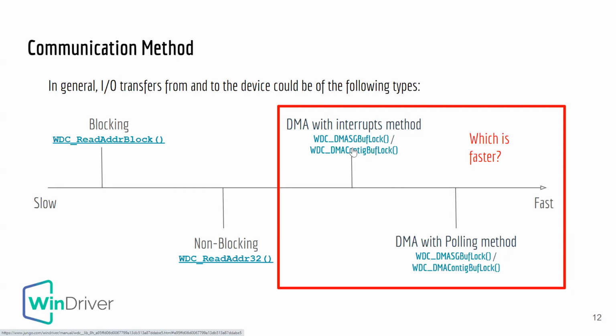So in this type of DMA, there is a transfer taking place. Once it ends, it raises an interrupt to the CPU instead of the CPU continuously asking for the status. So what is polling? Polling involves repeatedly checking a status flag or register to determine if a DMA transfer has completed. This method requires constant monitoring by the CPU, which can introduce overhead and inefficiency in handling data transfers.